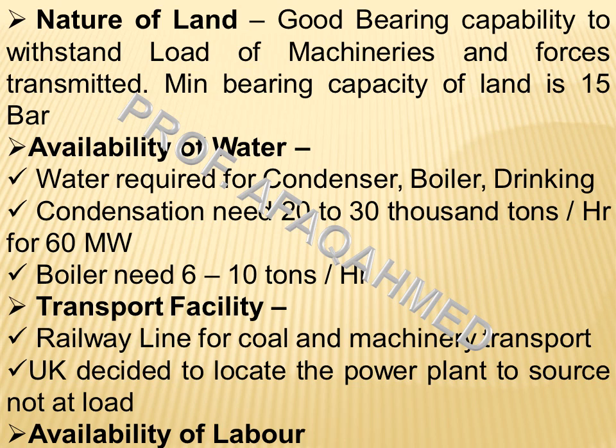So that is all about the transport facility. Now the UK has decided and reached the conclusion that it is more economical to locate the thermal power station at or near the pit head rather than at load centers. The transport of electricity is more economical for loads above 200 megawatt.